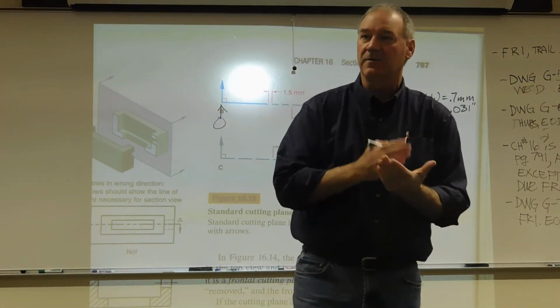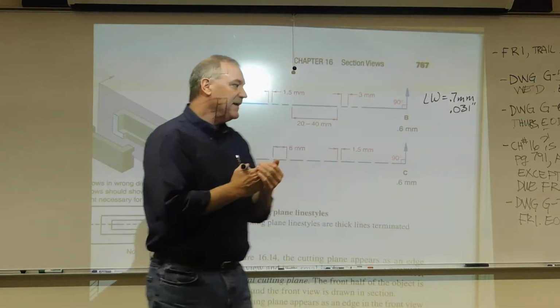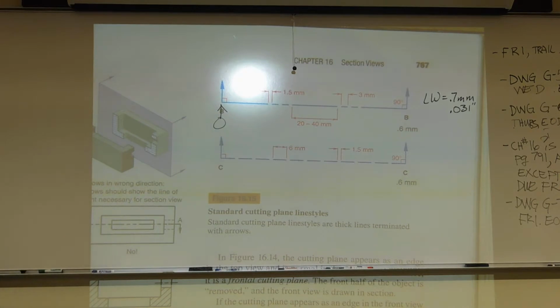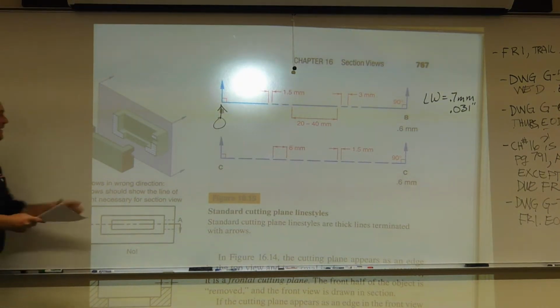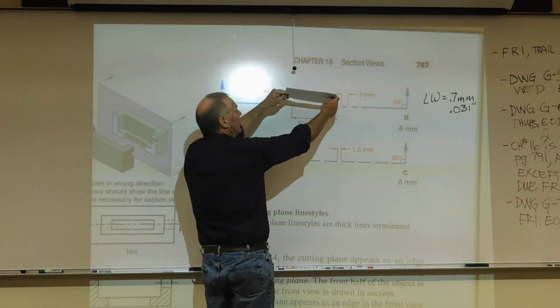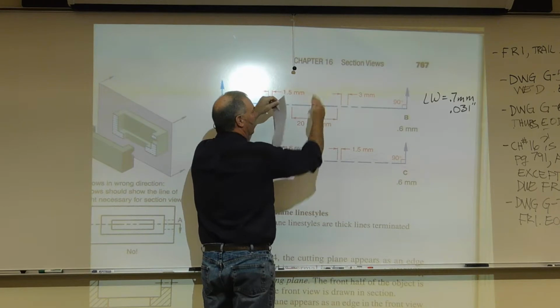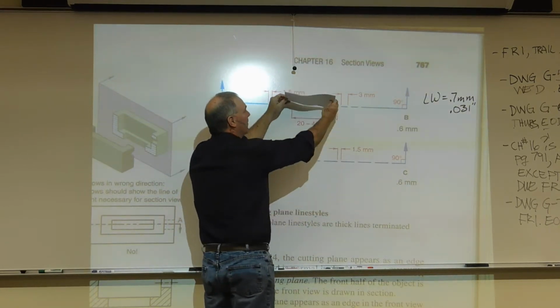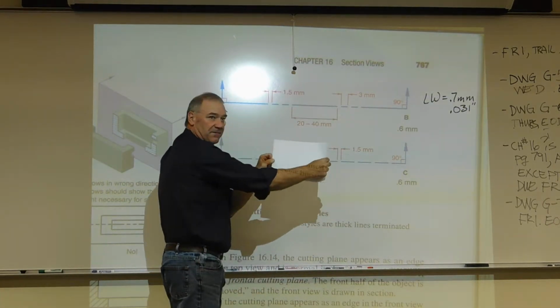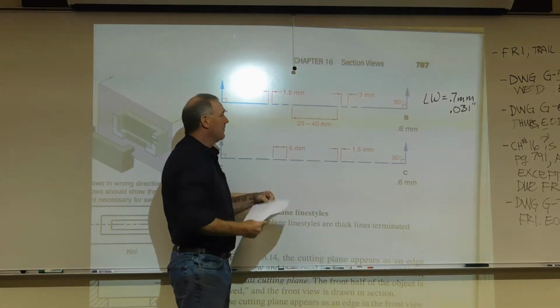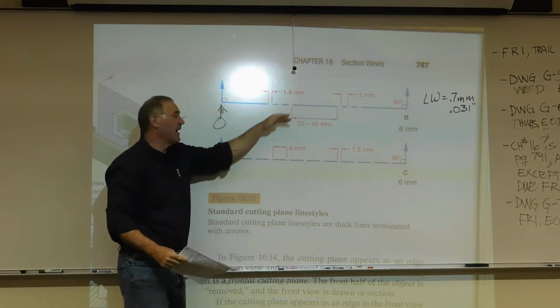So it's showing the location of the cut. Think of this line as really a plane. When you look at a section, you're going to see this in an adjacent view. What you're looking at here is a plane on edge. Now, when I'm looking this way, I'm going to say this is in my top view. When I rotate for the front view, that's where my section occurs. This one occurs in the adjacent view, tells me where it's at.